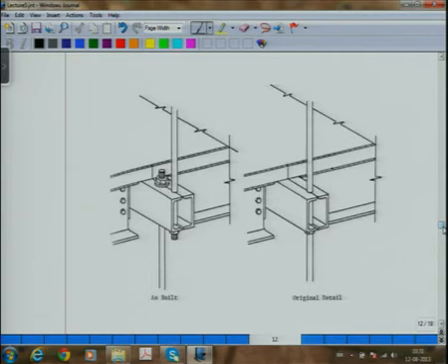From the top of the roof to the 4th floor, they put one shaft which was bolted here, and another shaft was put from the 4th floor down to the 2nd floor, bolted at the two ends. So this is how the original design was: one full long column bolted to the sides, and as it was built, it was replaced by two columns, and let me show that in a schematic way.